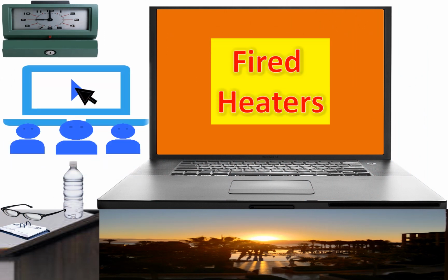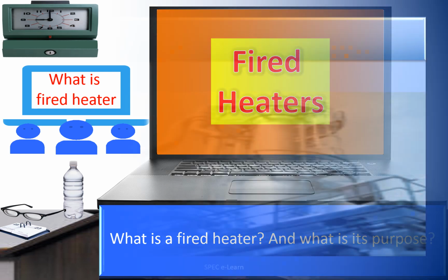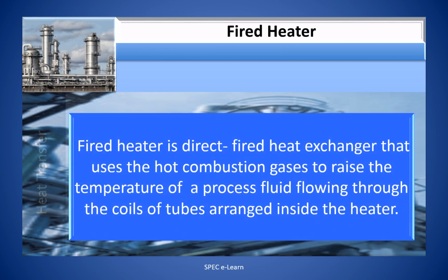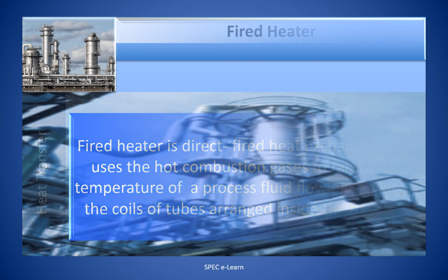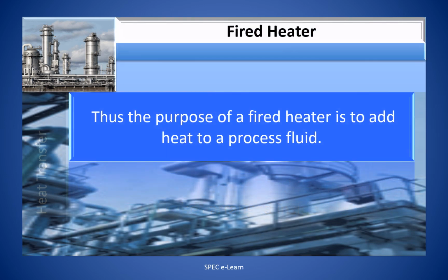Fired heaters. What is a fired heater and what is its purpose? A fired heater is a direct fired heat exchanger that uses the hot combustion gases to raise the temperature of a process fluid flowing through the coils of tubes arranged inside the heater. The purpose of a fired heater is to add heat to a process fluid.